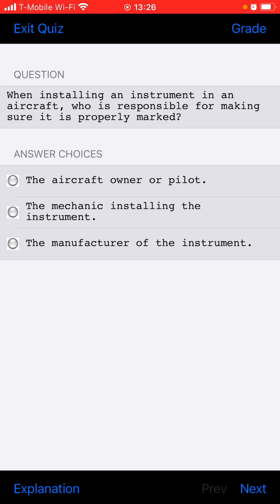Name two problems associated with in-flight operation of aircraft windshield wipers. Insufficient blade pressure caused by aerodynamic forces and failure to oscillate. Name two problems associated with in-flight operation of aircraft windshield wipers. Insufficient blade pressure caused by aerodynamic forces and failure to oscillate fast enough.